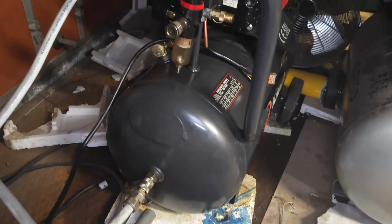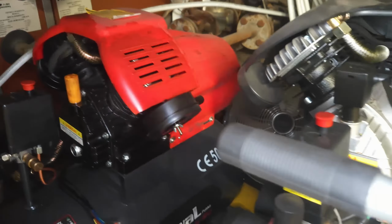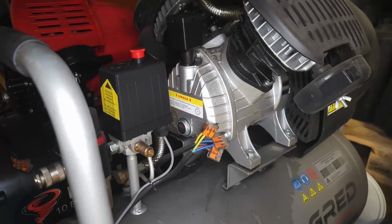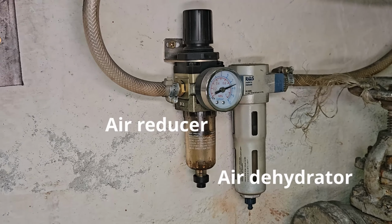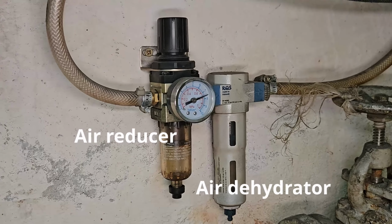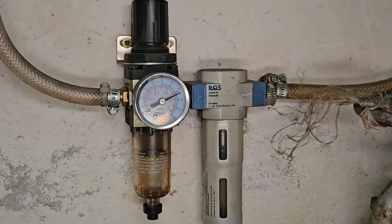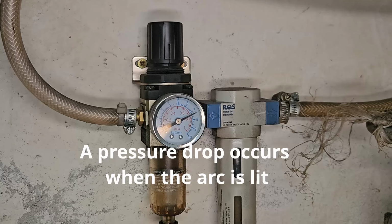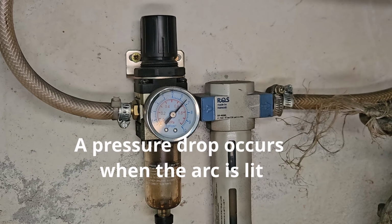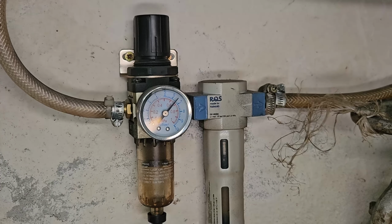Last but not least, we have compressed air. This one is extremely important and usually overlooked by people. The compressed air has to be dry, free of oil, and has to have a stable pressure. You cannot expect consistent cutting results when your compressed air is not consistent. Bad air quality will lead to more dross and faster degradation of torch components. So in conclusion, the compressed air you use must be dry and needs to have a constant pressure.